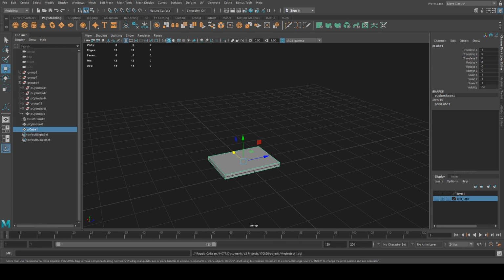So once I have these done, now I can set trim height. So the minimum here is ever going to go is actually going to be, let's set it to 0.5. And the maximum it's ever going to go is 3 meters. And we'll give it some extra resolution. And now we need to do that for each of these. So 0.5, half a meter, and maximum of 3 meters at a resolution of 0.01. Again, same thing. 0.5. See, can you do that? No, you can't do that with the open module. That would be too nice. 0.01. And this one we're going to do to 0.5 and 3 and 0.1.